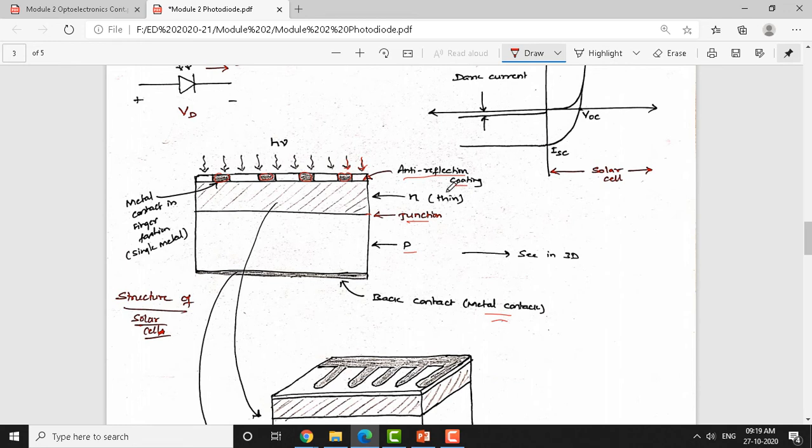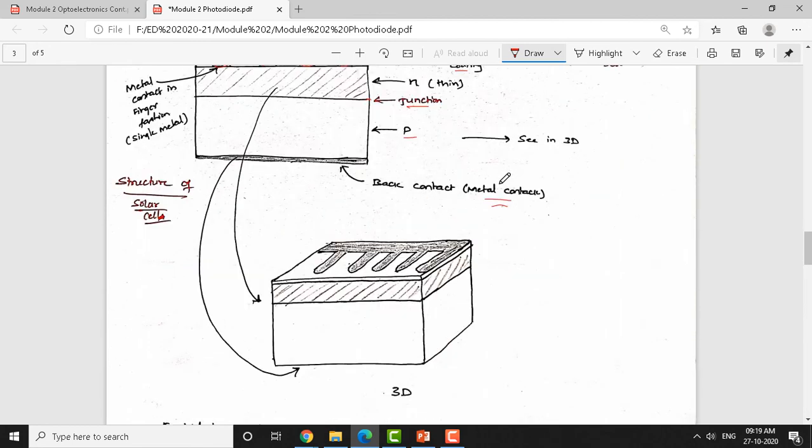Okay. So, this solar cell you must operate within this limit, as shown in the region of operation here. This VOC and ISC is the region of operation of the solar cell. Within this region, you can extract maximum energy from the solar cell. That means, in a sense, you can obtain maximum current from the solar cell if you operate within this region of operation.